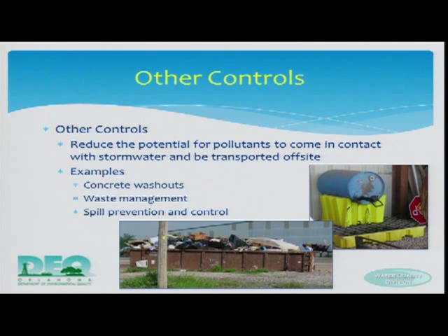You can reduce the amount of other types of pollutants that are leaving your site. Michelle had some pictures of some leaking drums and things like that. Be aware of secondary containment requirements that you may have in SPCC. And your concrete washout needs to be something that people are aware of. It's not a place to wash the truck out completely.